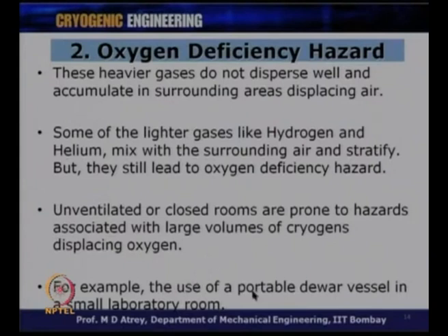you bring a dewar into your room where you want to do experiments, and everything in that experimental area could be sort of an air conditioned area, and therefore, it will not be exposed to the atmosphere. It will not have doors and windows open all the time. And this has to be taken into consideration while having these experiments at low temperature. If you are handling cryogens, you should always have doors and windows open to the atmosphere to ensure that a lot of air circulation is taking place around you.